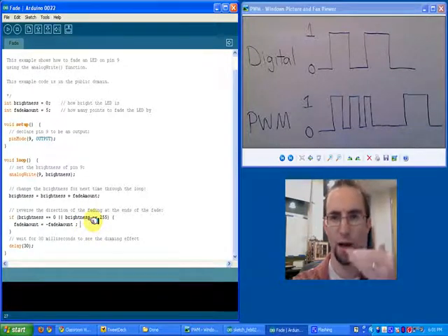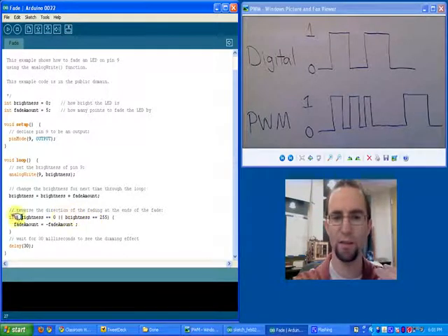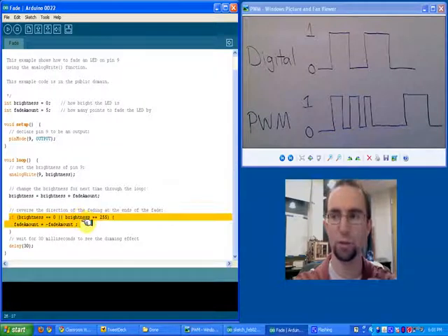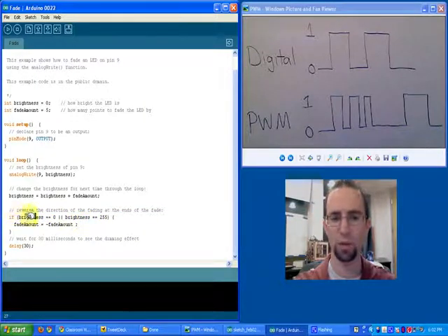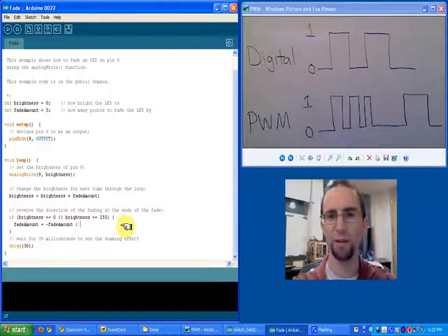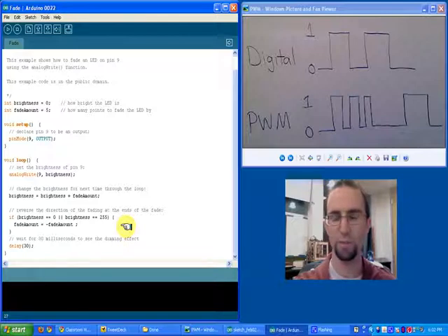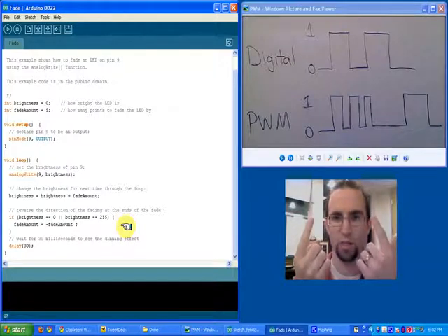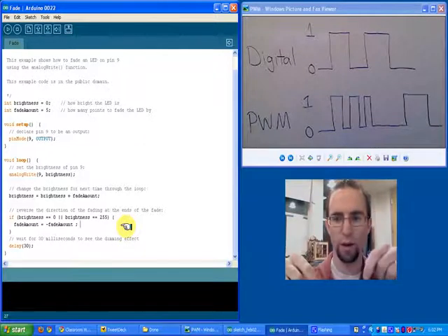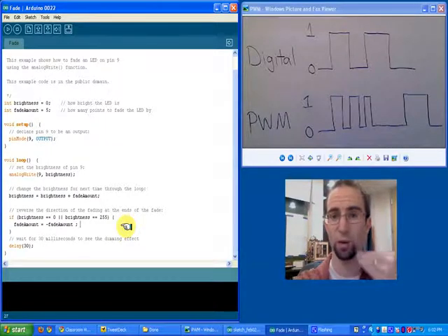So it goes 0, 5, 10, 15, 20, and so on, and then it gets to 255. That triggers the if statement, and that turns that 5 into -5. So now it starts going 255, 250, 245, 240, and so on back down to 0, and then again it will trigger the if statement again, which will turn that -5 into 5. So it's basically a vector. It tells the LED to increase upwards, meaning on, or downwards, meaning off, but by an incremental amount. That's that pulse width modulation.